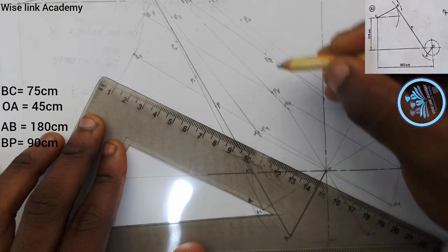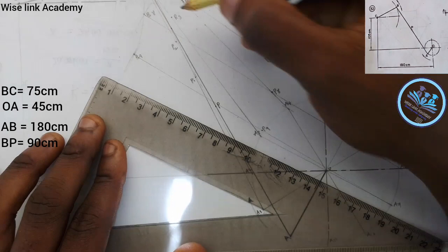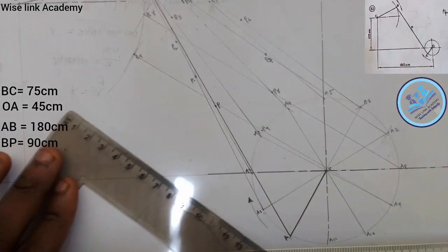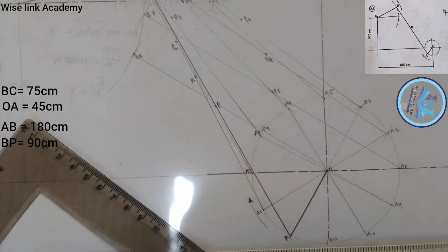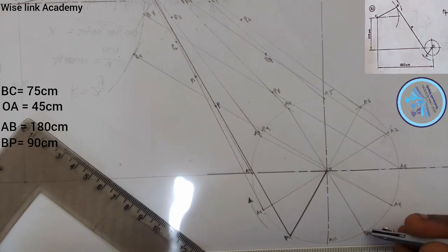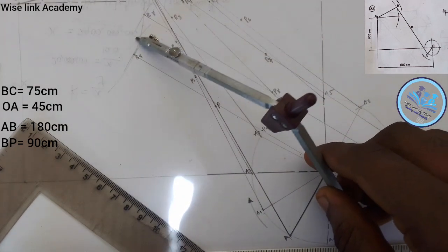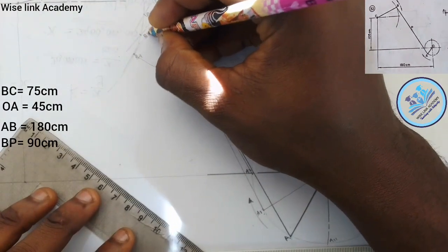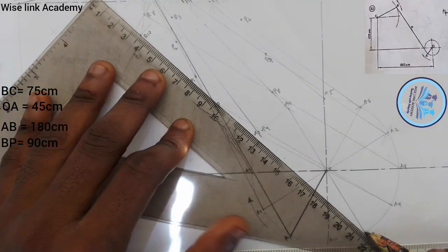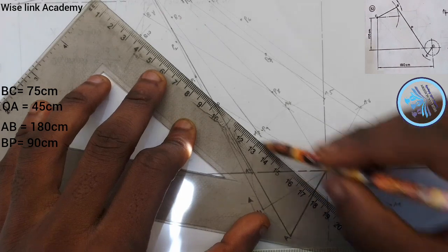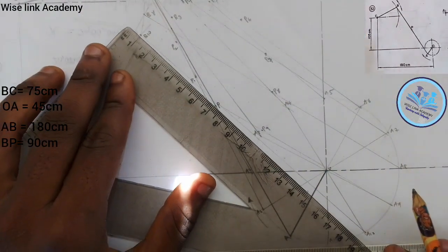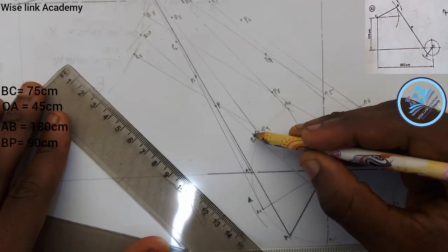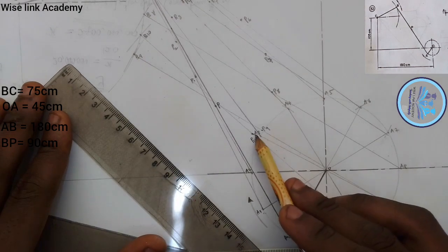Taking those points, so as not to get you confused, taking them very well so you see them when you want to use them. Next up is P10 and P11. So I'll do that simultaneously. At my point A10, I'll strike an arc on that arc here that I've drawn earlier. I'll call this my point B10. I'll connect B10 to A10 this way with a faint line. Then I'll measure a fresh 90. This point here is my point 90. So P10 is connected at this point. So P9 and P10 are connected together this way.